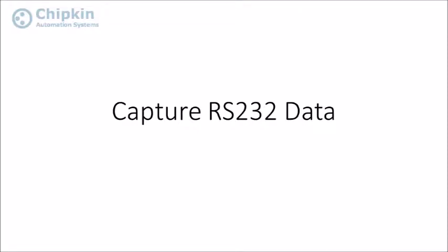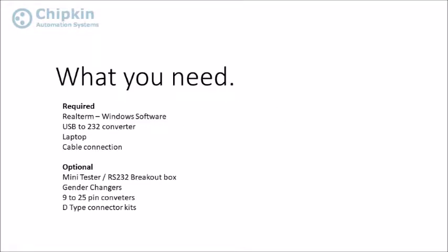I'm going to show you how to capture some RS232 data. This is what you'll need. I use Realterm. I used to use Hyperterminal, and I never came to love PuTTY, but I hear it's great, so feel free to use what you like. I need a USB to 232 converter, a laptop, and a cable to connect to the device that is transmitting data.